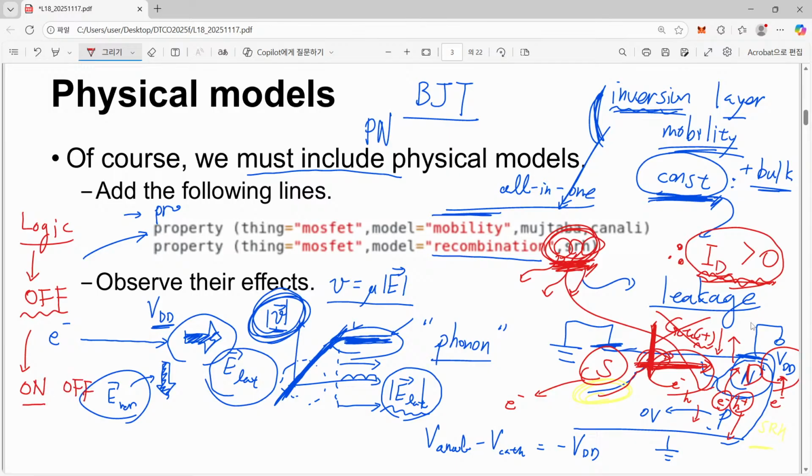In this case, since drain to source voltage equals 0, that is really 0 current. However, think about the opposite case. Now your gate is turned off. However, you are driving your drain with high voltage or low voltage depending on the polarity of your device.